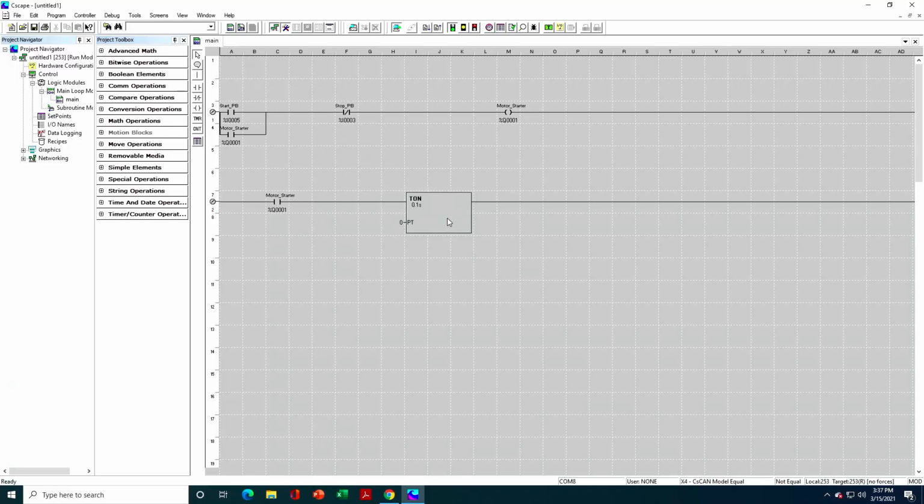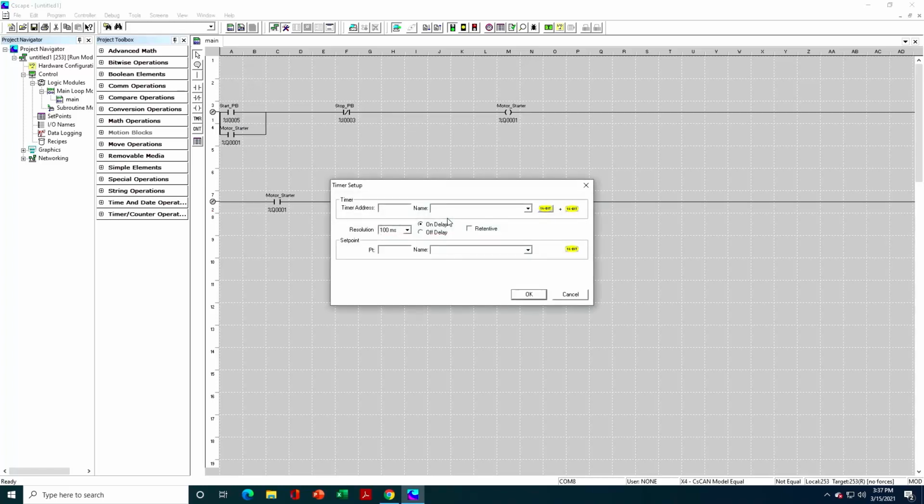All right, now, how do timers work? With some PLCs, and the OCS is a type of PLC, you have special memory address types for timers. The OCS isn't like that. The OCS just uses general purpose word type registers for timers, and it uses 2 of them consecutively.